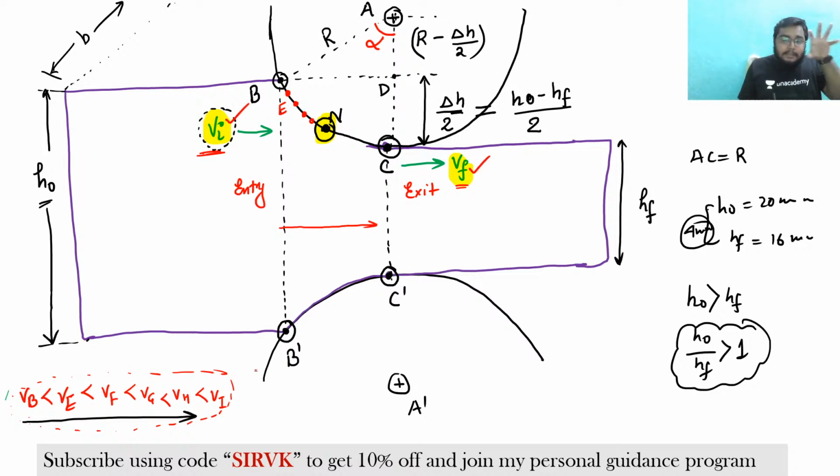So that simply means that the workpiece is fed from the entry section to the exit section. So from the entry to the exit, velocity is going to increase. Why? Because VF is more than VI. So if this point is B, and these are E, F, G, H, so I can say here that VE would be greater than VB, VF would be greater than VE, VG would be greater than VF, VH would be greater than VG.